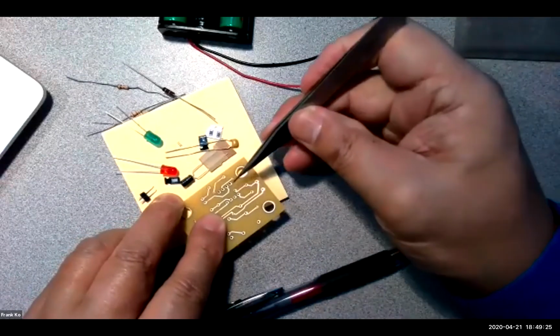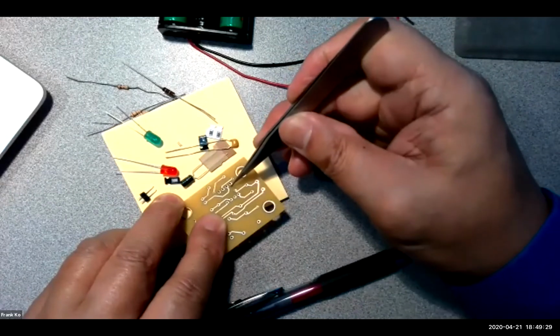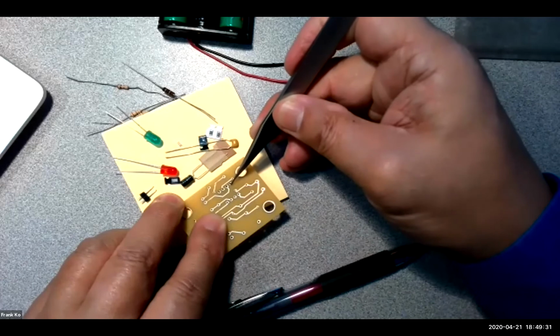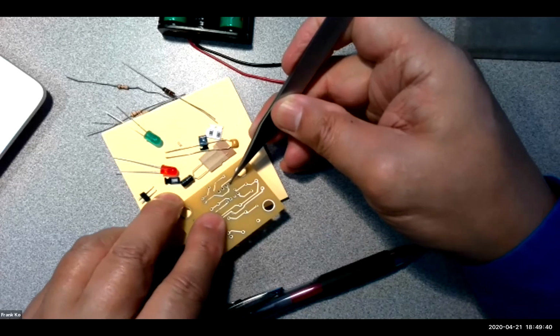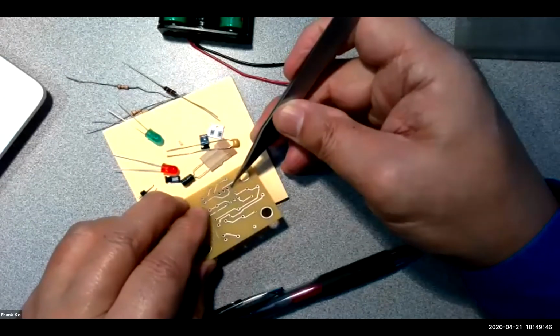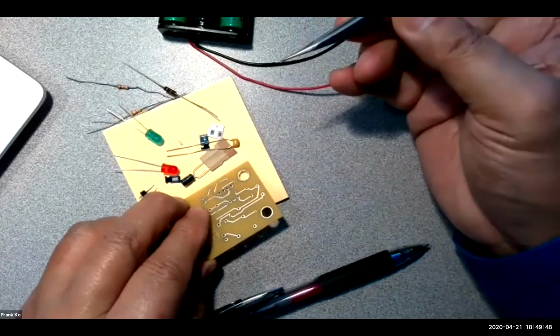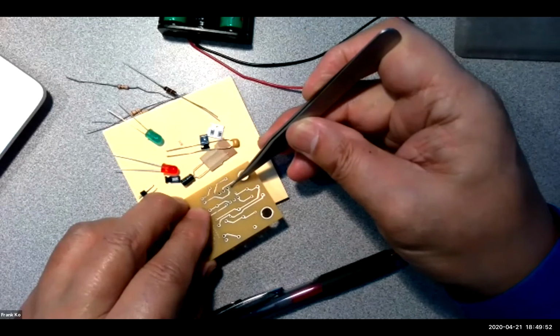If I'm going to come here and solder, I'm going to use not the point of it, but very near the point, because I have to heat both the trace and that chip pin simultaneously. And I count my 1001, 1002, 1003, 1004. Then I bring in my piece of solder and let that melt, and then I bring both away. So in this particular case, very near the tip, but not the tip.